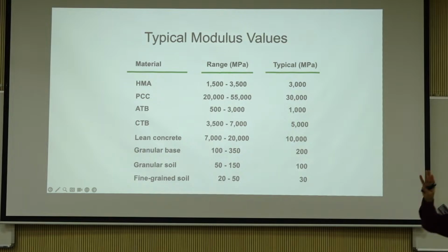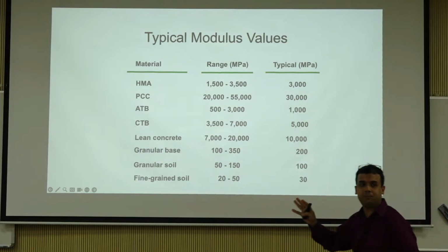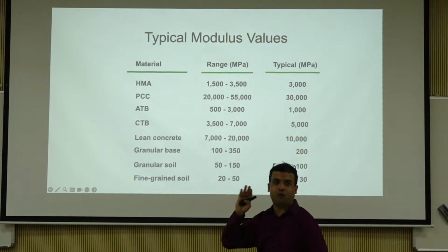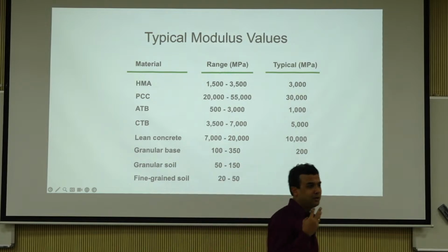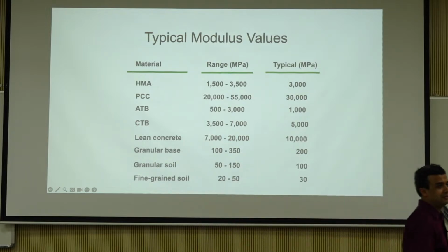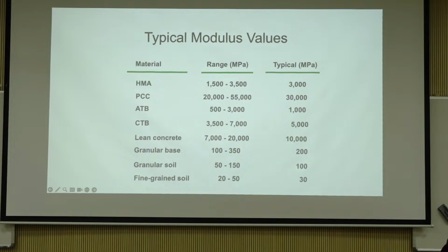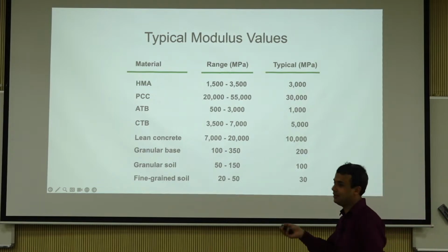If you take concrete, the modulus is 4 million psi. If it's asphalt, it's 400,000 psi. If it's aggregate, it's 40,000 psi. If it's subgrade, it's 4,000 psi. The representative number, you will get by with 90% of the cases. Subgrade 4,000 is a little bit on the lower side, but 4 million, 400,000, 40,000 are very, very good guesses for E values if you're doing pavement design and stuff. That's how I use it.